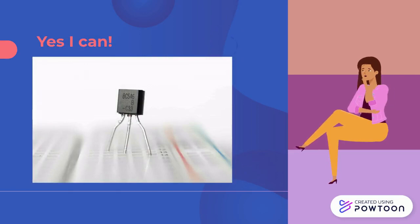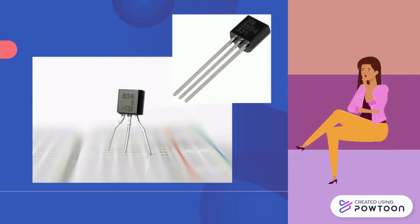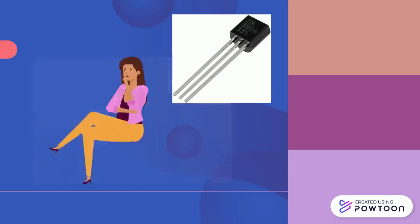A transistor is usually a black, plastic cylinder with one flat side and 3 pins. When holding the transistor with the flat side facing towards you, count the pins from left to right. Pin 1 is the collector, pin 2 is the base, and pin 3 is the emitter.